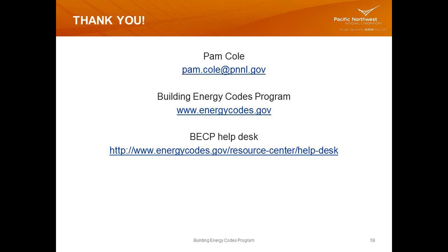The next question that came in: how does exterior rigid insulation affect the moisture on a basement wall? Isn't insulation supposed to be installed on the warm in winter side? It depends on what climate zone. I definitely refer you to the IRC on basements; insulation and moisture can be a big deal depending on the location that you're in and how you insulate. Do you have an air film in between, like concrete masonry? Do you have an air film to let that wall breathe? Where are you insulating that wall? Do you have water management for that wall?